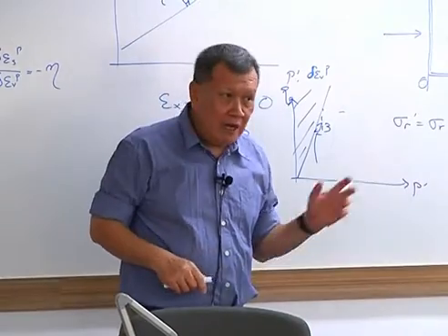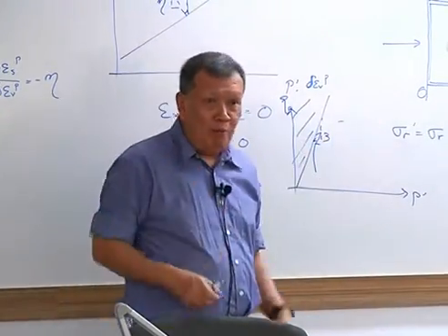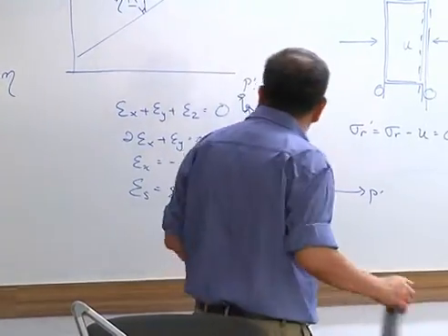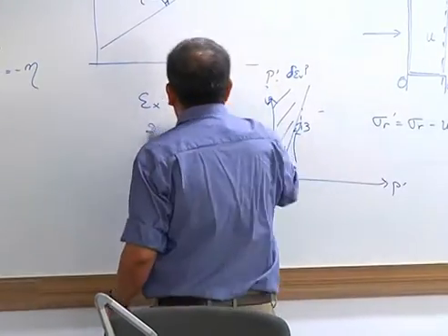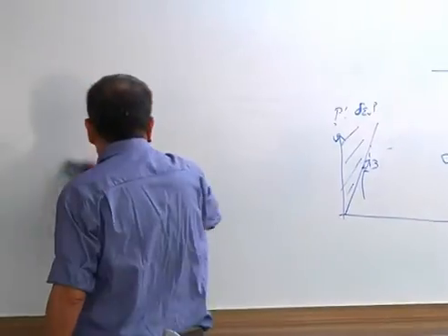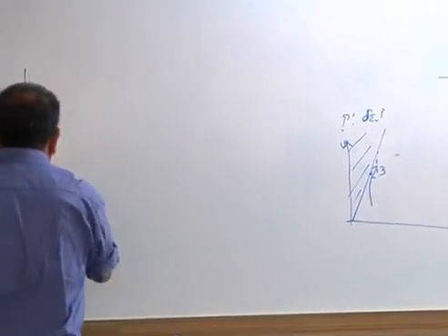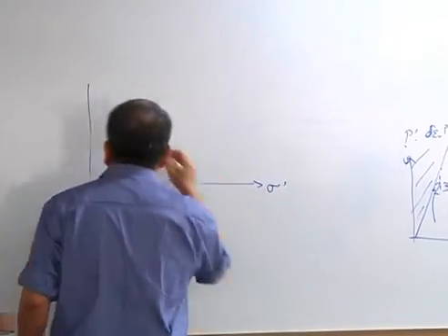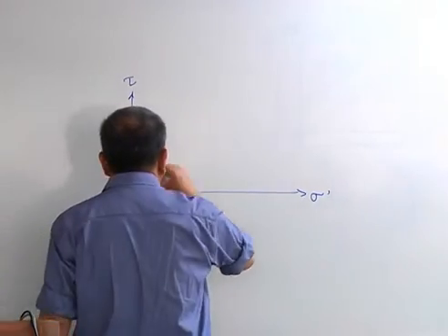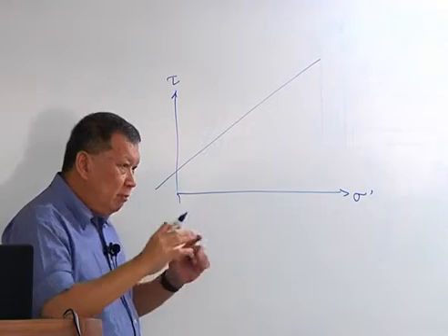Okay. Now you actually have a similar limitation even if you plot it on the standard Mohr-Coulomb framework. I can tell you where the limitation is. On the standard Mohr-Coulomb framework, the limitation occurs here. This is the standard Mohr-Coulomb plot. And you might say, okay, there is actually a failure envelope here, and you draw the Mohr circle.